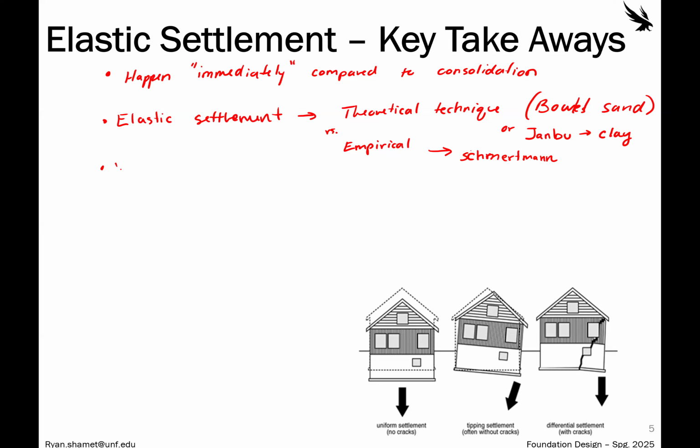When it comes to consolidation settlement in clays, most of the time these would all be experimental techniques. So it's neither theoretical or empirical. You're going to be doing consolidation testing and recreating the settlement that you would expect to feel in the site. Now we're starting to dive into a little bit of empirical techniques for consolidation, but still at the end of the day, the tried and true method is the consolidation test to estimate consolidation settlement.